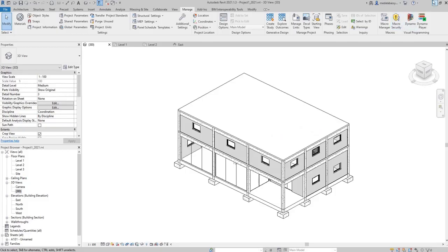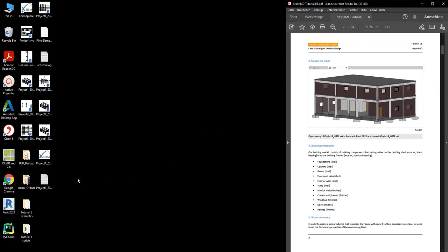Now it's done, so you can check on the desktop and you'll see the file here. You can check the file size just to make sure it has exported everything. You can open it with an IFC viewer to make sure the model is already exported properly. But if the file is too small, then you have to make sure that the export layers settings are set properly.